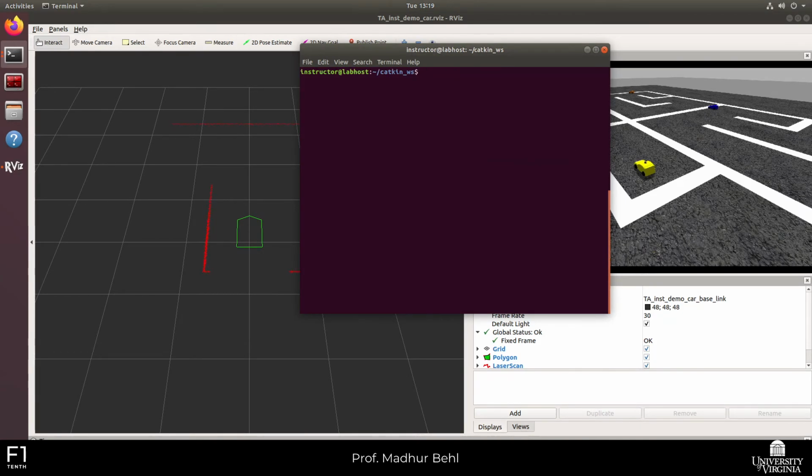Now I want to show you how to ensure that this template code is going to work for you, right? By the way, as an exercise, I should say source catkin workspace devel setup.bash. You should always source your environment, remember, because I don't know if it has been included in the bashrc yet. Now we can navigate to the code that I just showed you.